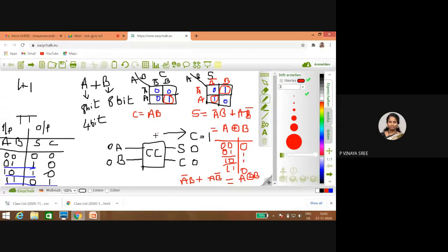Okay, is it clear? So next step is what? Note down in your notes the design statement, the designing for half adder. Why am I saying half adder? Let me explain after completion of all this. Our main design is to add two single bit digits, and the corresponding result will be sum and carry. For that we started with the problem statement. With this we identified that there should be two inputs and two outputs. Based on that we designed our truth table.